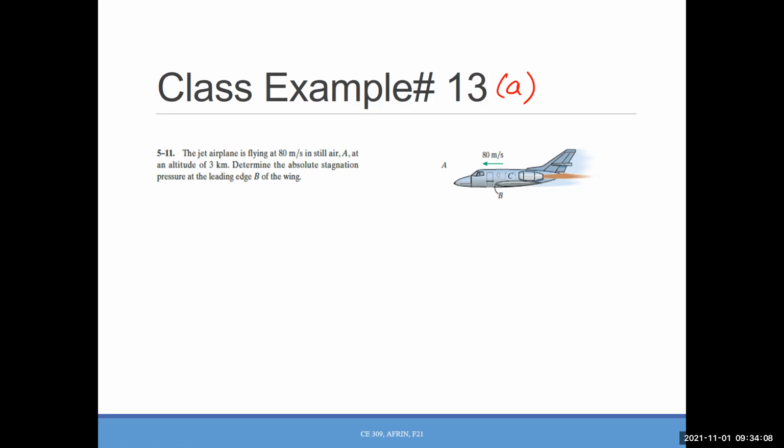Now, for Bernoulli's equation, we said that it is for incompressible fluid, and most of the time incompressible fluid is liquid, because the definition of incompressible fluid is that the density is constant, right? For gas, like this case, we are working with just a strip of air, and we are not applying any heat or changing the altitude, so the density is kind of constant here. So we can treat this problem as an incompressible one, and that's why Bernoulli's equation can be applicable for this case.